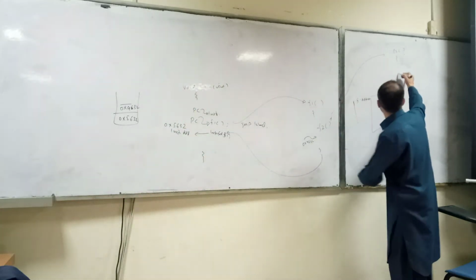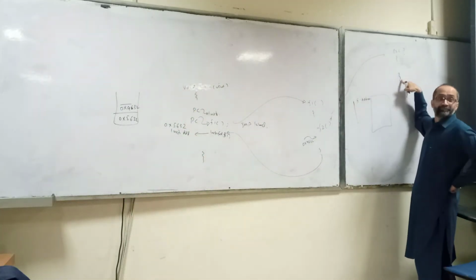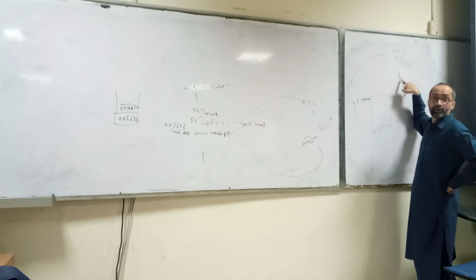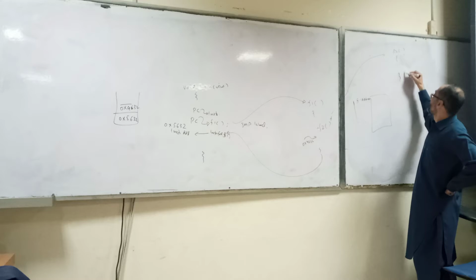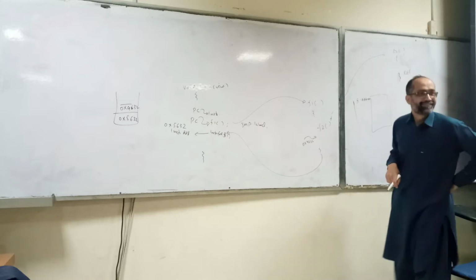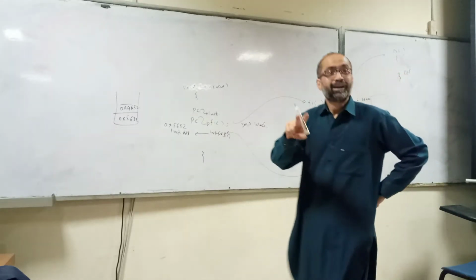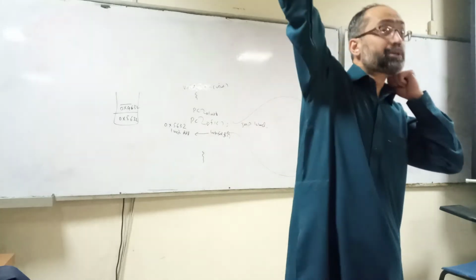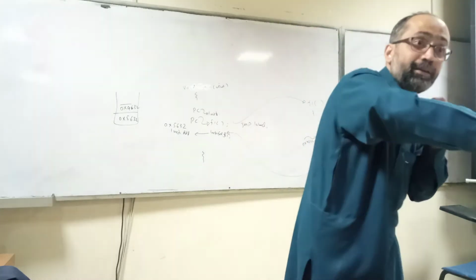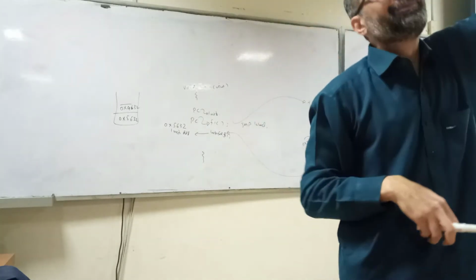Now when you execute the last instruction, what is the assembly equivalent of this? If you remember, RET, return. Return is actually a hint that whatever program counter value was pushed on the stack will be retrieved back and the program counter will be updated.